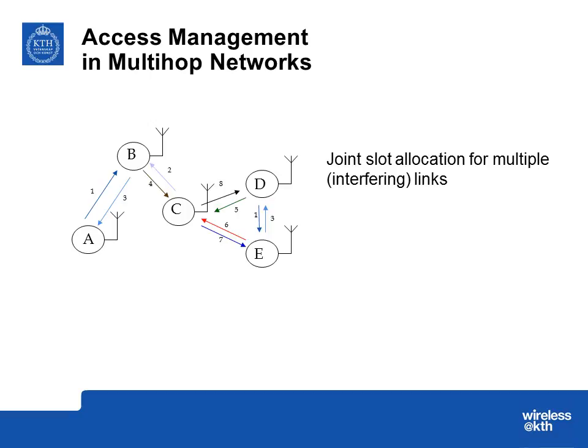And we will look at two types of scheduling schemes. The simplest one is, of course, the transmit schedule or node schedule, where every transmitter gets allocated a time slot, like in this case, where nodes A to E each get one time slot, and in this time slot they can transmit the messages whichever their intended receiver may be.